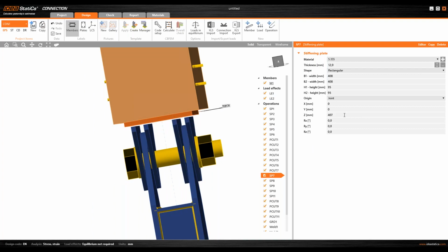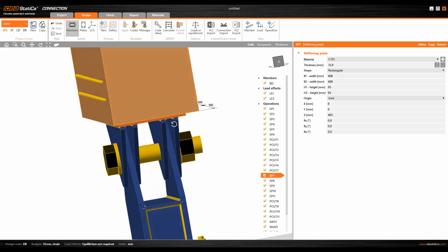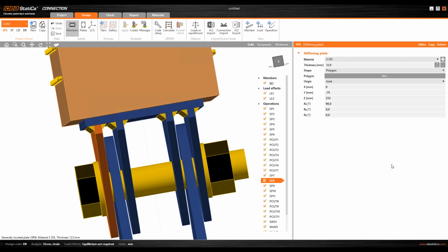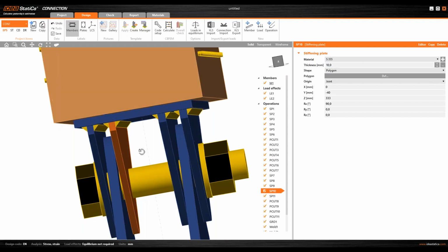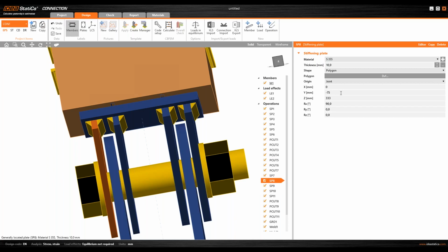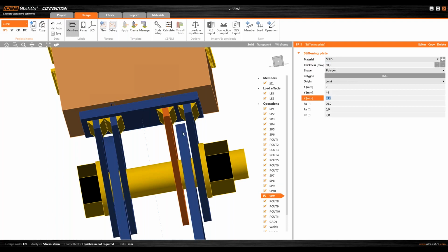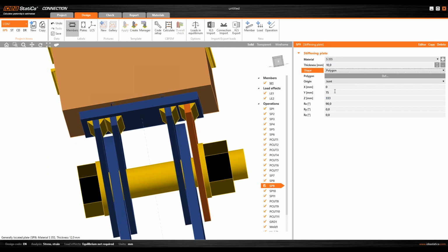Getting a gap here, so I have to shift it a couple of millimeters to get the connection back in there. And the ribs, now 10. Let's try 10, and also I'll shift them a bit to -72, and this 4 millimeters towards. Okay, like this and like this.